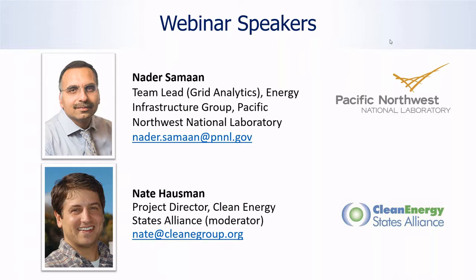So there are several approaches. We are presenting here an optimization coordination between all these devices together. Some other approaches use group control, where if anything changes, all of the smart inverters change simultaneously. There are a couple of different approaches. But I think PV developers are more and more willing to let utilities control their smart inverters.